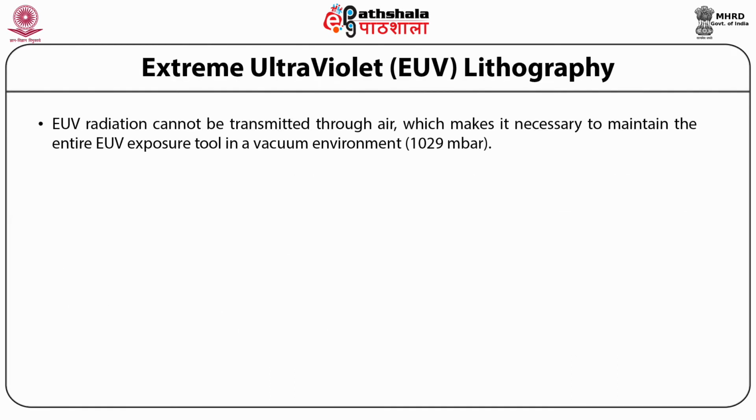EUV radiation cannot be transmitted through air, which makes it necessary to maintain the entire EUV exposure tool in a vacuum environment. So, outgassing of resist and components of the exposure tool inside the chamber therefore poses a significant contamination risk to the EUV optics.